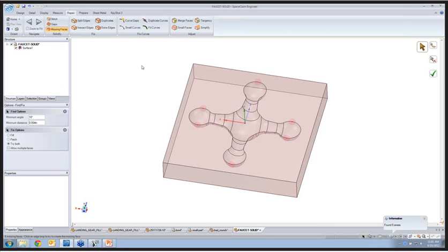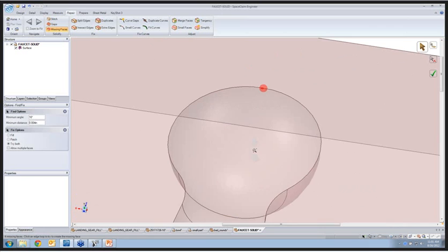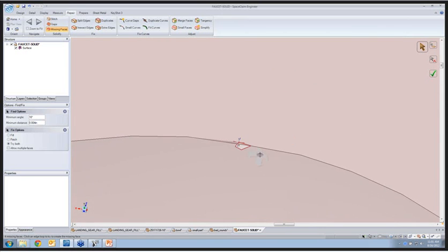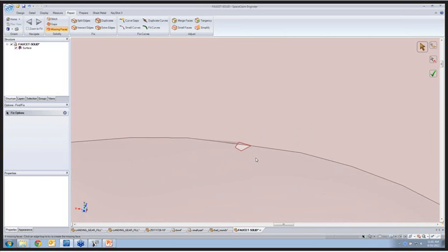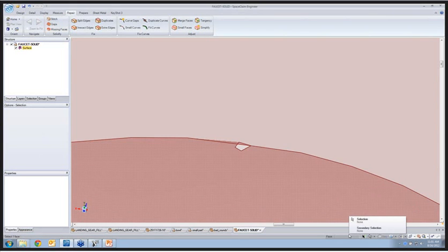This found 6 missing faces. So I click the green check and heal as many of them as I can. It says at the bottom that only 2 of them were fixed, so 4 of them were not fixed. So I zoomed in to try to figure out why, and it turns out these aren't actually pure missing faces. It's not the appropriate tool for healing these areas. If you look closely, you can probably see there's a little bit of a shadow line. It doesn't show that well right now.